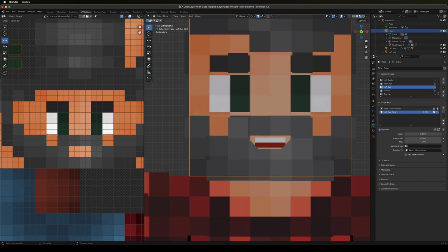Once done, if we go back into object mode, we can now select the shape key and move the slider for value to see the deformation we just introduced and see it animate. A full value of 1 is movement to the full range of deformation introduced.